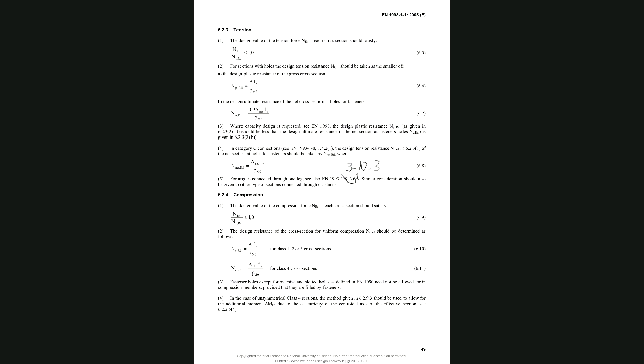we go to Eurocode 3, part 1-8. So the hardest thing about the Eurocode is just trying to navigate yourself around it. You go into the tension clause, you do a couple of checks, then it sends you back up to find out what gamma M0 and gamma M2 are. You have to go to a different place for that. To find out f_y and f_u, you have to go to table 3.1. So it's really just about knowing where to find the various parameters that you need.